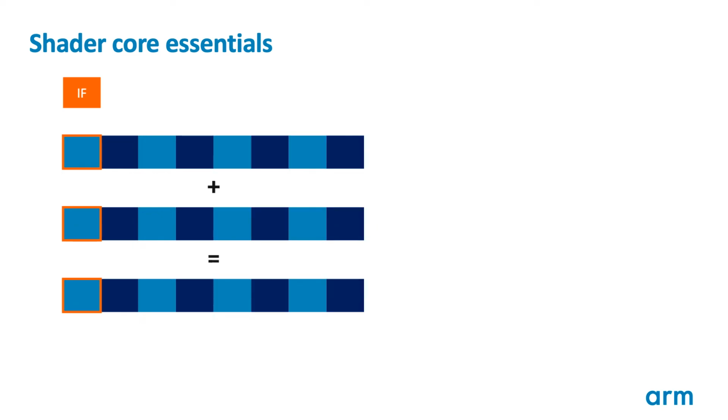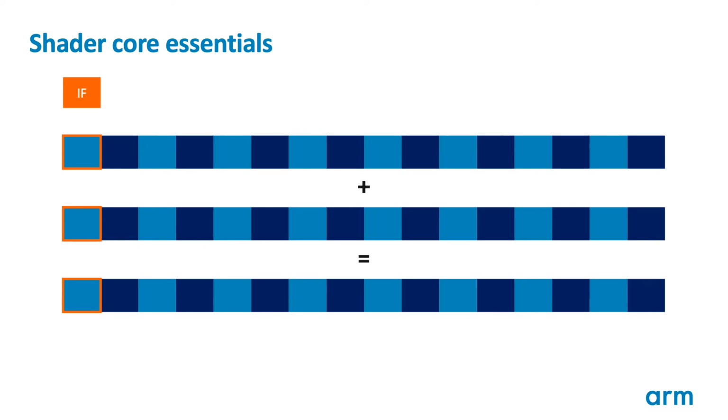The good news with this approach is that the vectorization width is no longer dependent on the program being run, provided we have a problem with lots of threads. We can further increase the warp thread count to 8, 16, or even wider to further amortize the control plane cost over the more data processing operations.